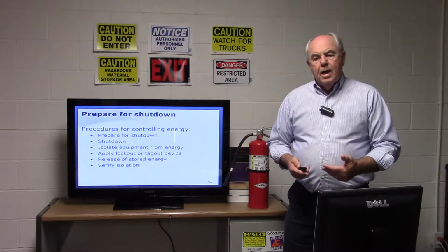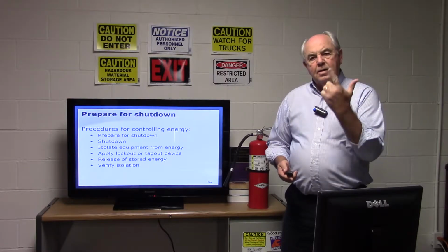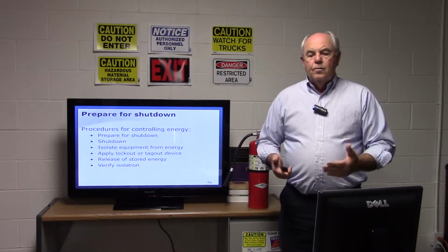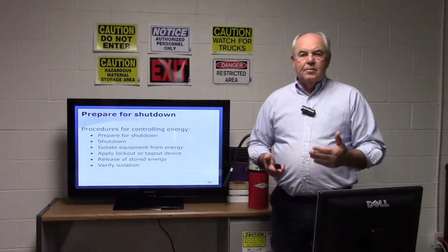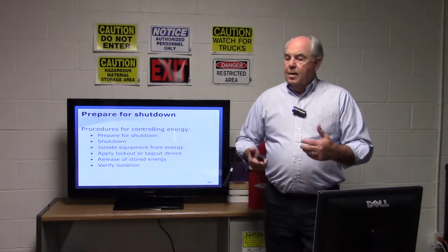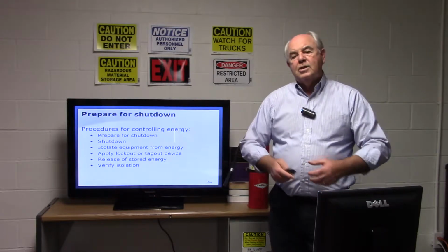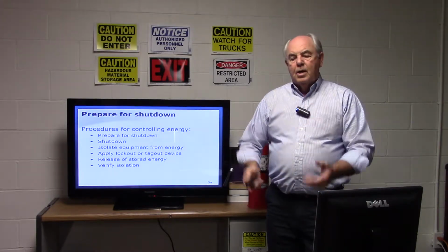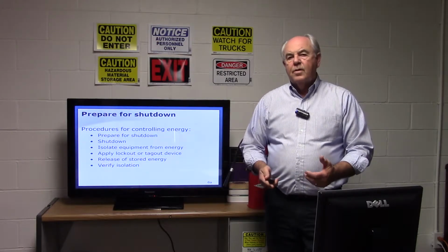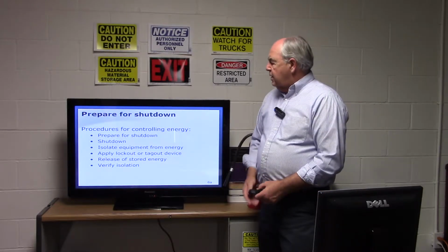I'm working right now with a group down in South Alabama where a gentleman just lost 3 of his fingers. These 3, here's how he speaks to you now. The bottom line was, if you feed your hands into a piece of equipment that's operating or into a machine that's running, that's the kind of results you could possibly get. But if you will utilize lockout, tagout, and make sure that machine is shut down, make sure it is stopped, make sure the energy sources are off from it, it is the safest thing you can do. So let's look through the procedures right quick.